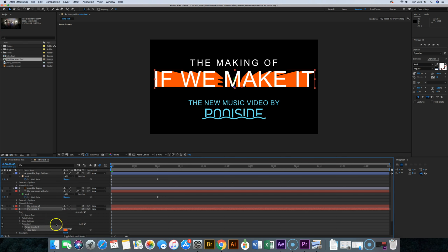So to the right of Animator 1 we have an Add button and a right arrow, and we're going to click on that, and we're going to affect the property of the side with transparency this time. So Property, Side, Transparency, and in that value we're going to add 50% transparency. And once that processes, you'll notice how the extrusion has a visible white and opaque back face.